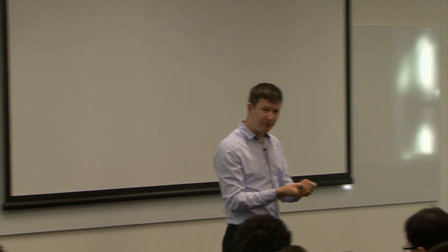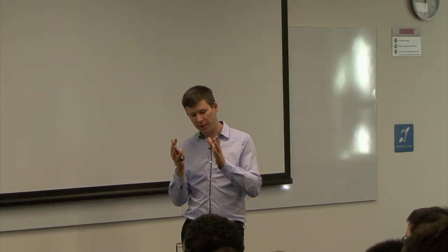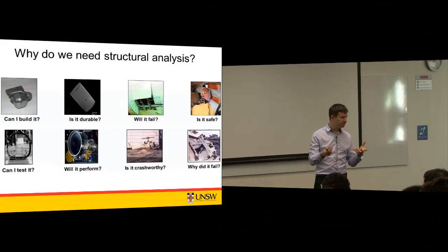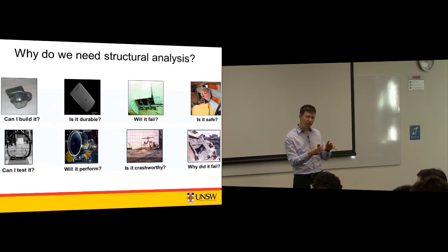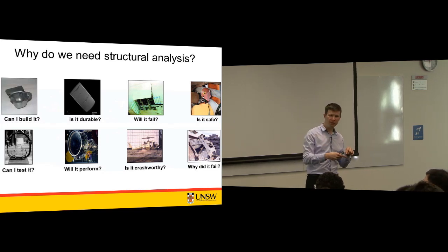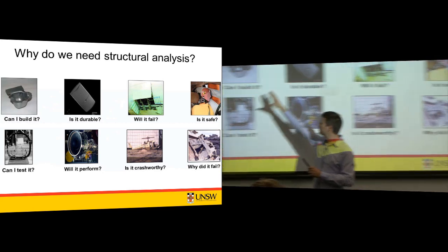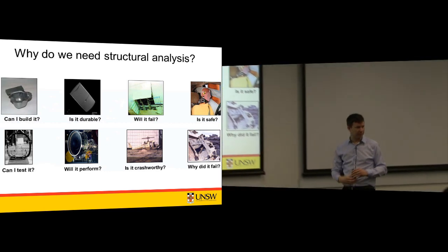That's really tough to do analytically. If you start with an end shape in mind, the question is, because you know that things have elasticity, you're going to stamp it and it's going to spring back a little bit, right? What shape does your die have to be for you to achieve the end shape that you desire? That's a really tough problem to solve.